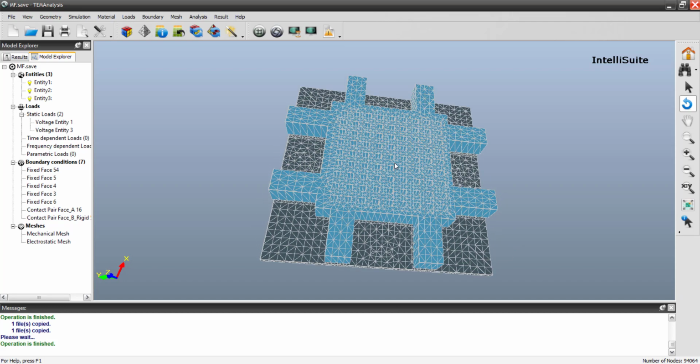So why did we do this simulation of pull-in analysis? Because in electrostatic actuation, we generally apply voltage. When the device is capacitive based, whether the sensitivity is due to capacitance or due to electrostatic force of attraction, we need to know at what voltage the pull-in will happen.